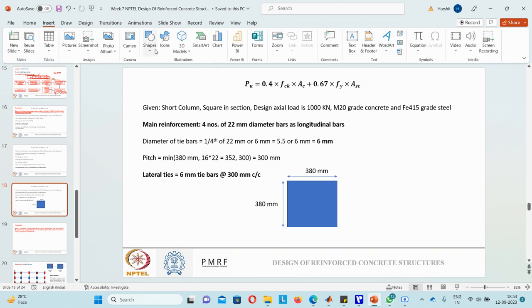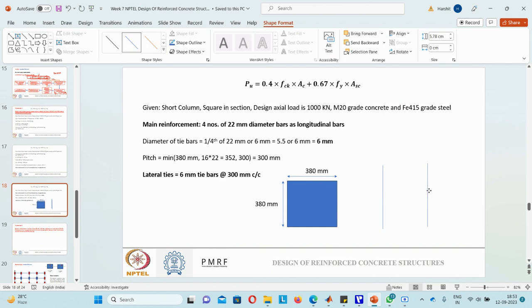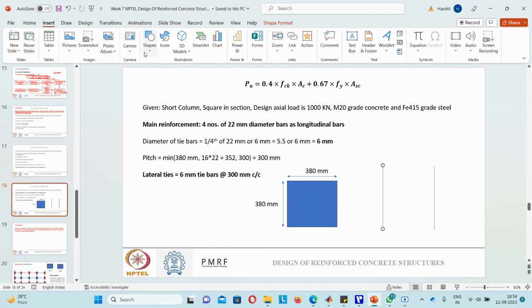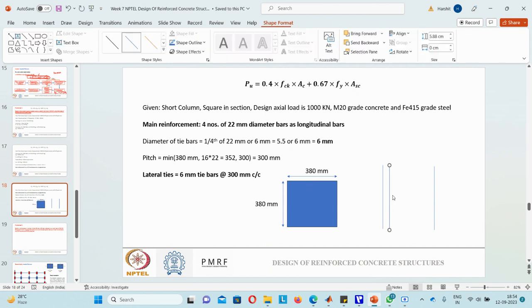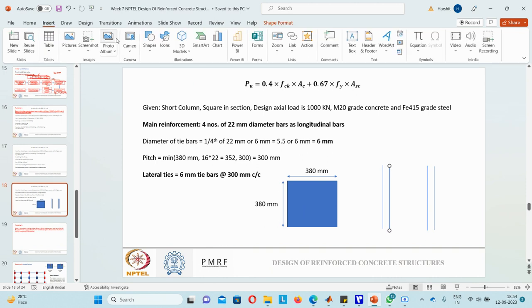And if I look at the reinforcement detailing, suppose this is the edge of the column. If I am providing a spacing of say 40 mm from the side, my longitudinal rebar will be somewhat like this, running at a gap of 40 mm throughout the length. This is my longitudinal reinforcement, running close to the edge of the reinforced concrete column, and this distance can be 40 mm.